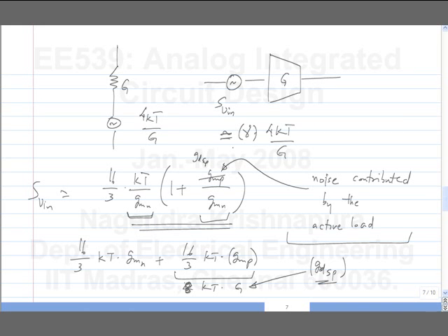Yeah, that's correct. But, okay, what about it? No, I mean, it's not enough to have just a large value of resistance. That will give you a small current, but what about signal? I think the assignment problems discuss these things, right? You are interested in the signal to noise ratio, not in just the amount of noise. If you use a high impedance circuit, your signal current is also smaller. So the signal to noise ratio will still be bad, although the noise is lower.